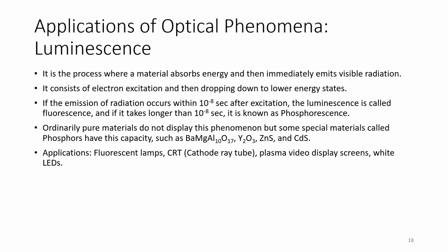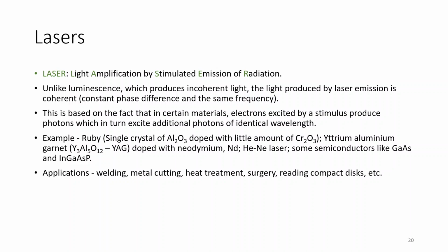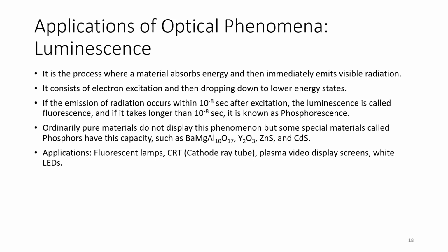Next is applications of optical phenomena. So the first phenomenon is luminescence, then the second is photoconductivity, and then lasers. In luminescence, it is the process where a material absorbs energy and then immediately emits visible radiation. It consists of electron excitation and then dropping down to lower energy states.